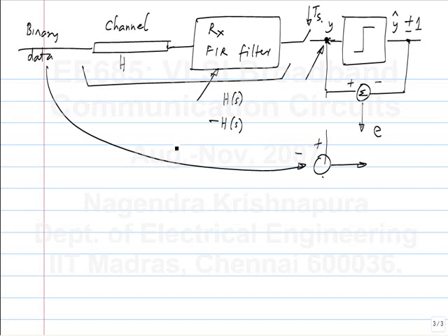If the total number of taps in the channel response is less than 7, then by covering all the possible 7-bit patterns, I have covered all possible ISI cases. Is that okay or not? Yeah, it is linear.